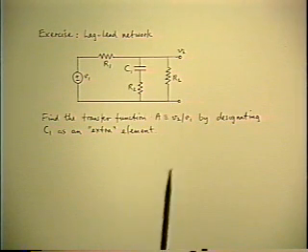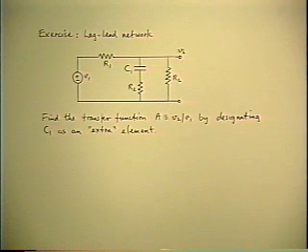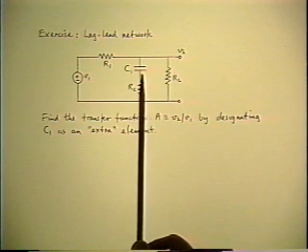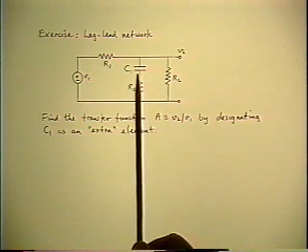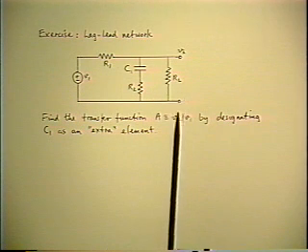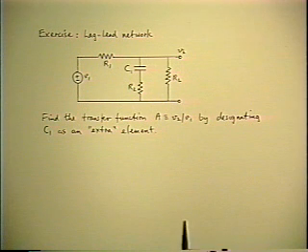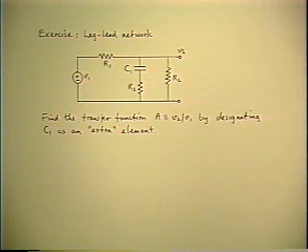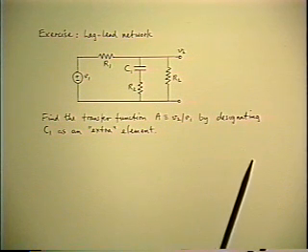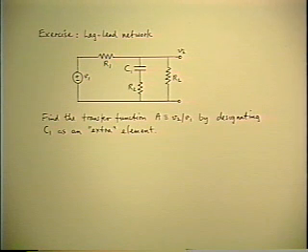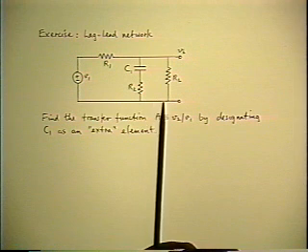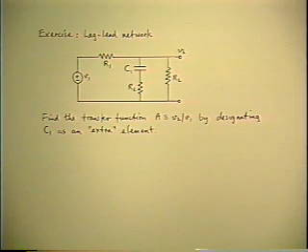So designate one of the elements as extra and throw it away. And according to the latest principle, the obvious element to choose is the capacitor. Throw it away, and then what's left is a purely resistive network, and it becomes almost ridiculously easy to solve for the reference gain and the two driving point resistances. All you have to do is put the capacitor back into the correction factor, and you've got the answer. Well, this is so easy that I won't even do the example. You try it right away.